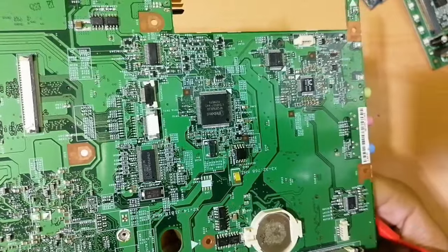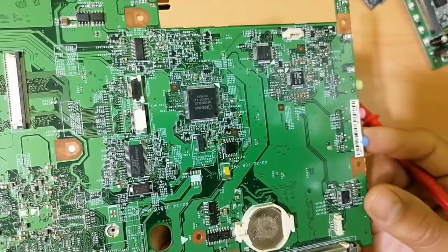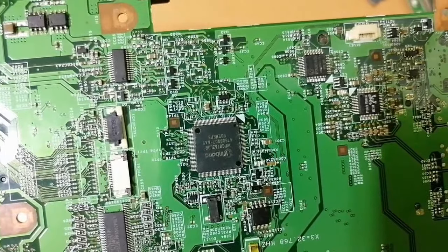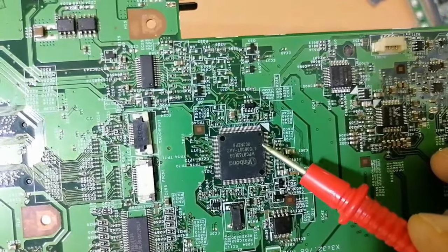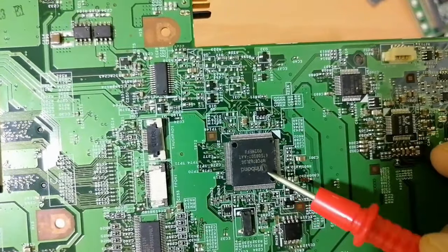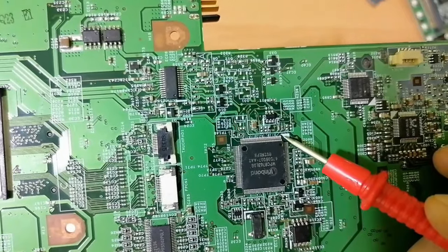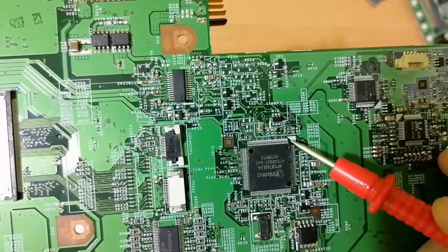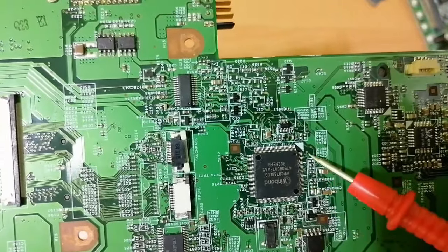First, let's discuss how to identify pin number 1 of the IC. For any IC, as you can see, you will always find a hole over here. For example, for this one we have this hole over here. We have those here too, but this is the hole. That means this is pin number 1. Or we have this triangle, as you can see here. So this is pin number 1, pin number 2, 3, etc.